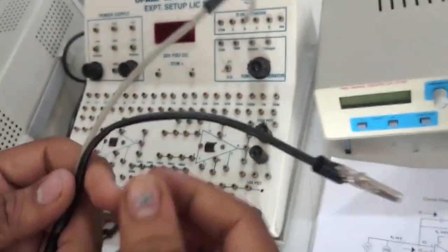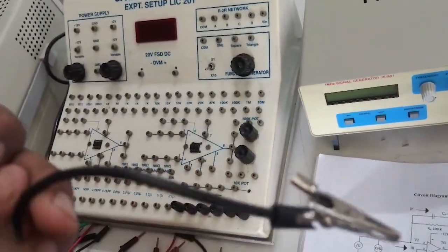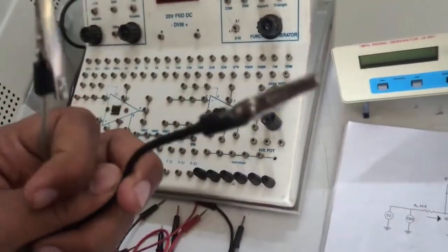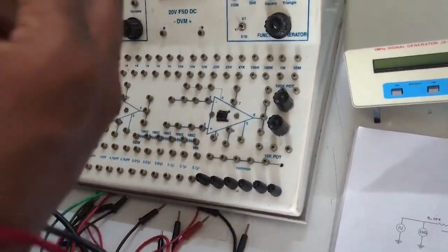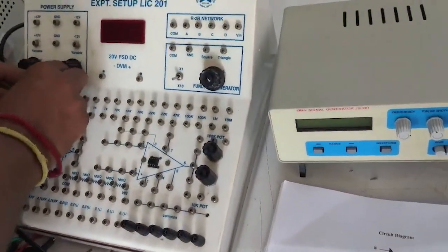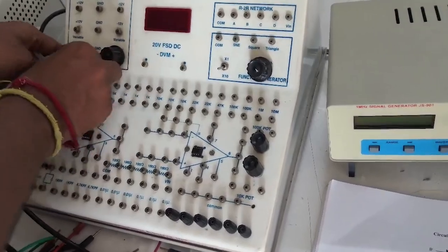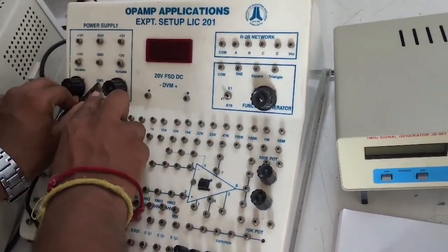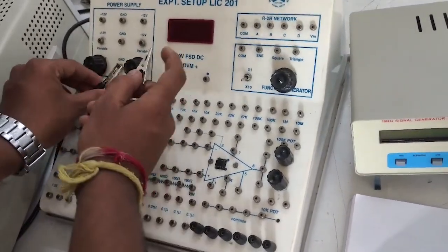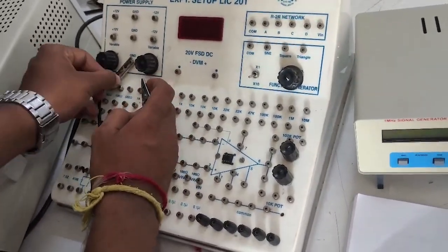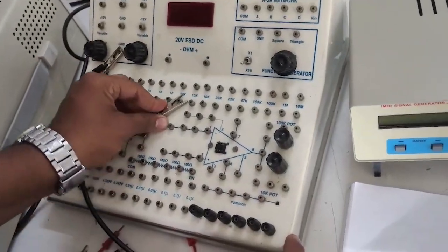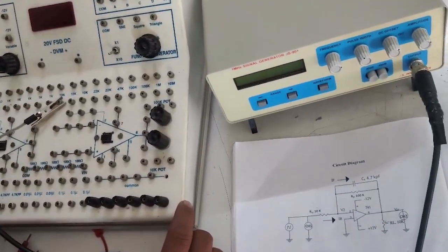In this audio oscillator, always black is negative and the other color is positive. Assume it to be positive even though it's not rightly colored. Now you're going to take the audio oscillator and ground it, connect it to some ground point, and once it's grounded, I'll tell the next one. And the other end of the audio oscillator goes to the 10 kilo ohms resistance.